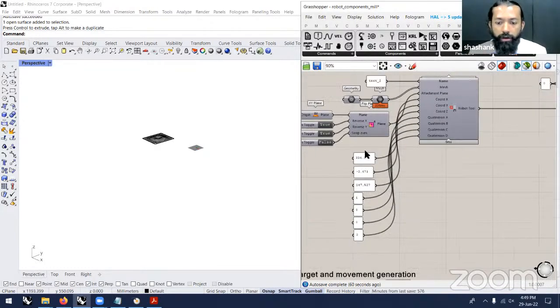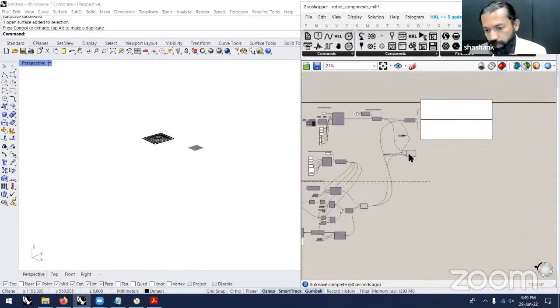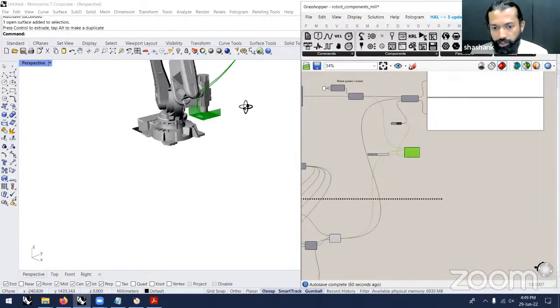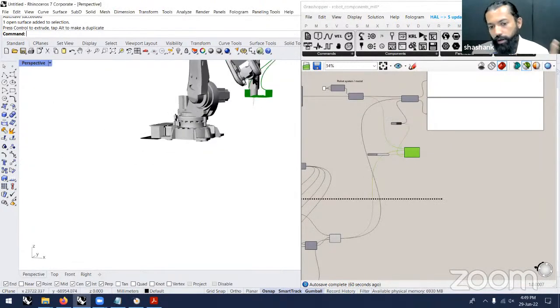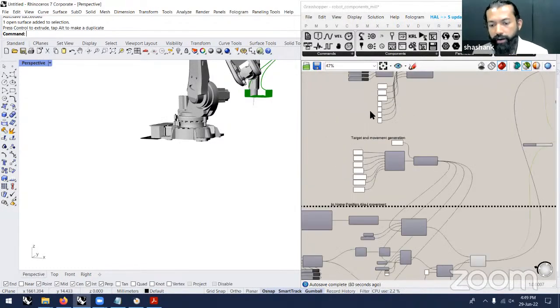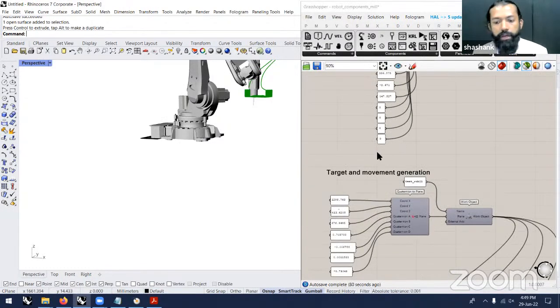So this is not a point of concern, because in many cases the model of the tool might not be accurate. Sometimes we just have a simplistic model just for indicative purposes, and that's perfectly fine as long as the TCP coordinates and the work objects are fed in accurately.